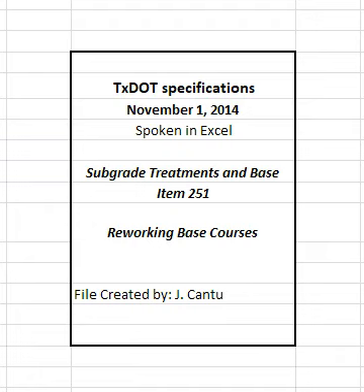Place salvaged material on the prepared subgrade and sprinkle, blade, and shape the base to conform to the typical sections shown on the plans or as directed. Place new base material and uniformly mix with salvaged material when shown on the plans. Correct or remove and replace segregated material with satisfactory material, as directed.